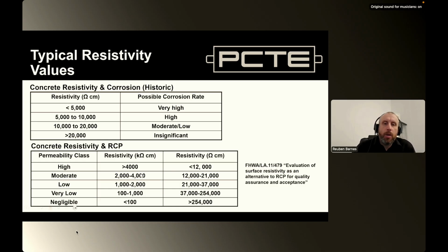And this data set indicates, and it's been proven because they're very similar tests, that they correlate extremely well. So in a lab sense, there is a logic to replacing RCPs with resistivities. And then potentially you could use those out on site, making sure that you take into account shape and size effects and things like that. So it could give you that link between your lab results and what's actually going on out on site, particularly with new builds and quality control and all that type of thing. In an investigative sense, not so much.